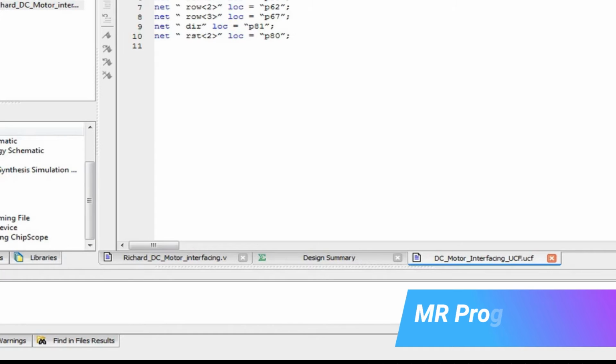Placement and routing is one such important parameter where we place components. We try and place those components which have a lot of connections very close, and those components which do not have many connections between them, we can place afar. So this is what happens in placement and routing, and this is a repetitive process, which means it keeps going on and on till it comes to an optimum design. I'll be showing you in the upcoming sections how we implement design.